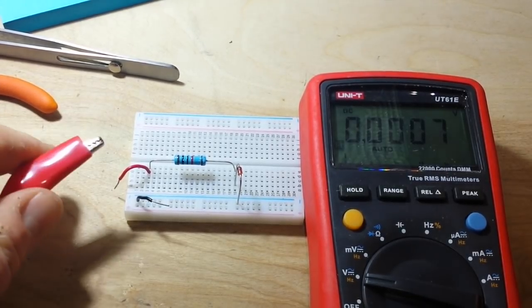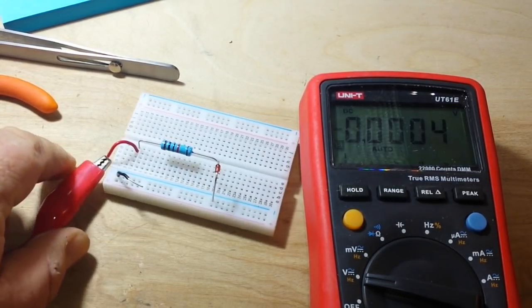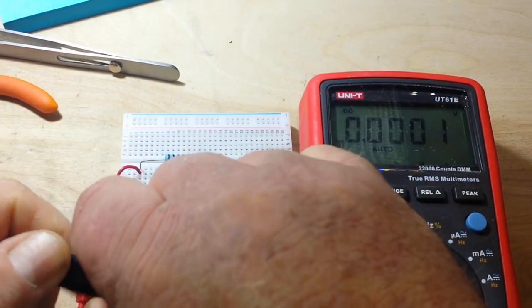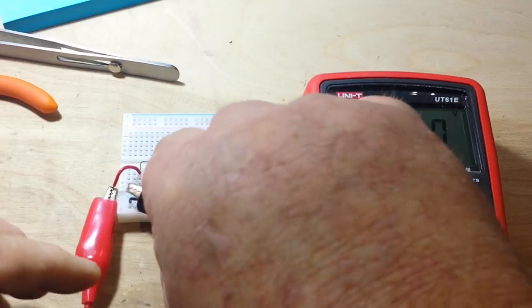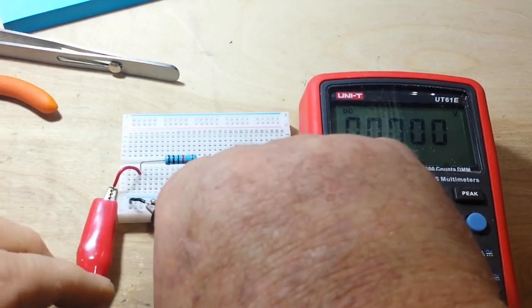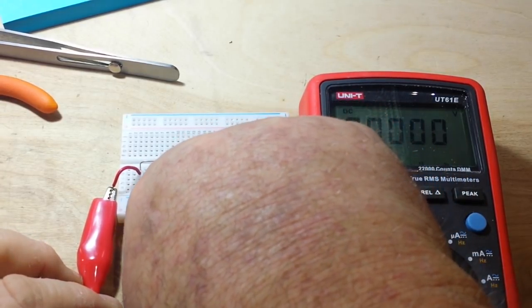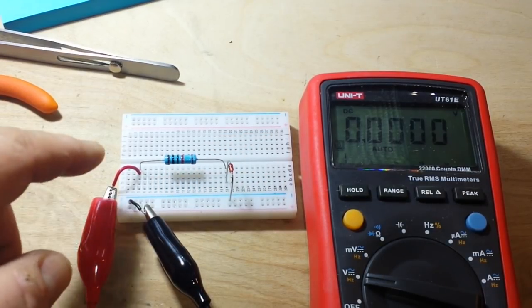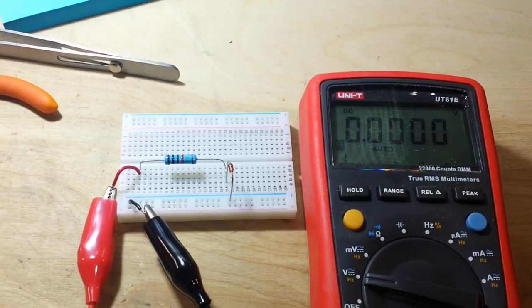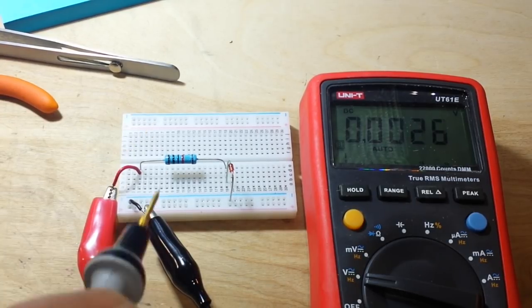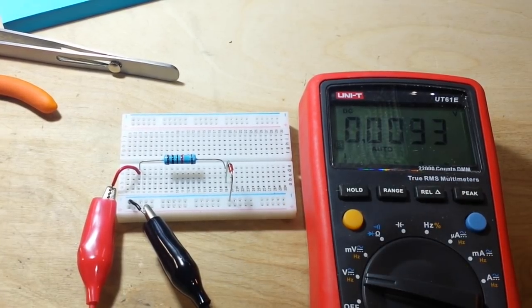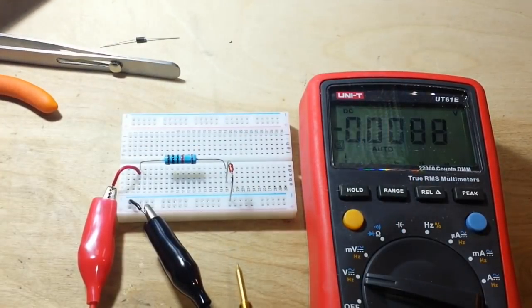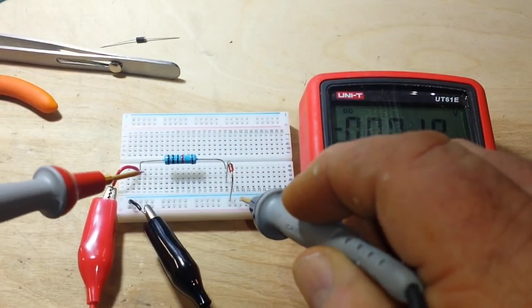So I'm going to hook the power supply up to our little circuit here. If I can get my fingers to work. Plastic, rubbery, slippery. Okay. So we're now reverse biasing that Zener at 9 volts. And we know that when we reach that mystery voltage, it won't conduct any further.